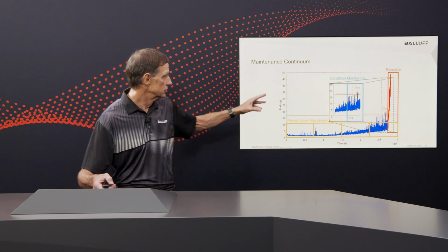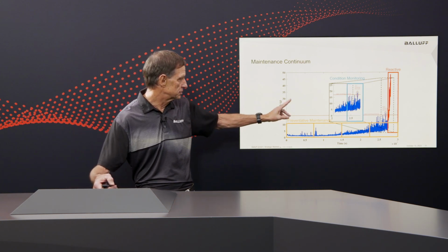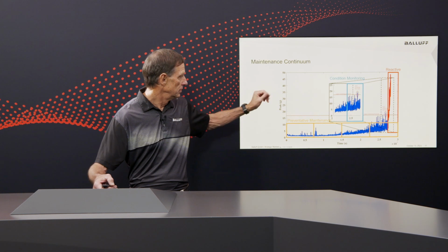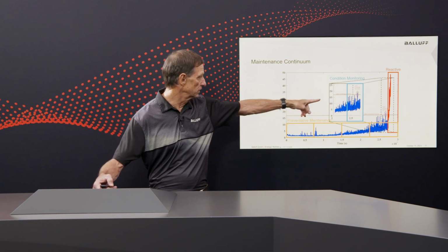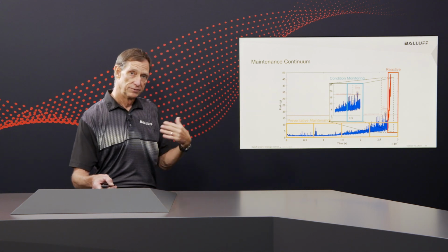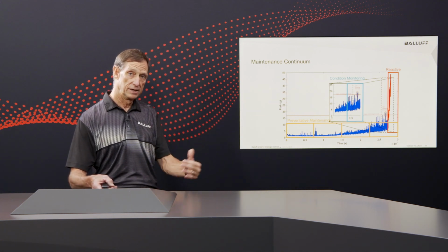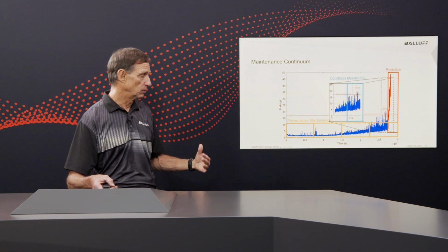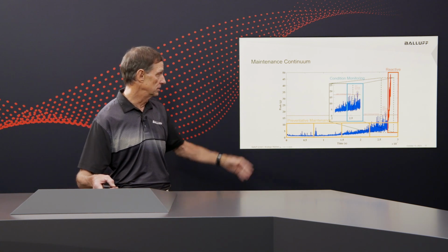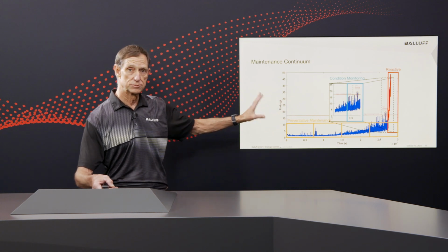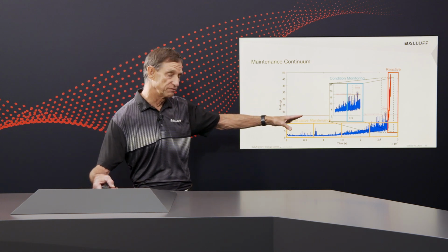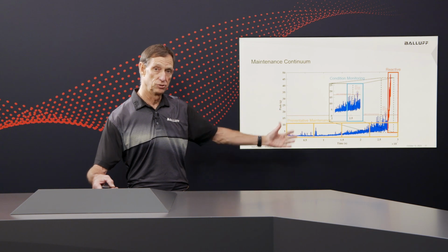Condition-based monitoring starts to look at the specific vibration pattern here and will start to send warnings when you exceed a specific limit. The challenge here is setting that limit at the right level and recognizing that alarm and then taking action. In this case, the limit that was set gave about a week to 2 weeks worth of warning before the catastrophic failure, so there would have been some time to address this issue.